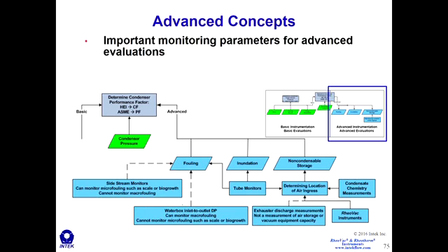There are other tools to monitor macrofouling. We highly recommend using water box differential pressures. I'll show some examples of how this is made and talk about the right way to make this measurement. There are also tube monitors. Tube monitors can be used to monitor fouling, and there are other uses for tube monitors. These are instruments that are installed in the outlet water box, on the outlet end of the tubes, and they monitor individual tubes.